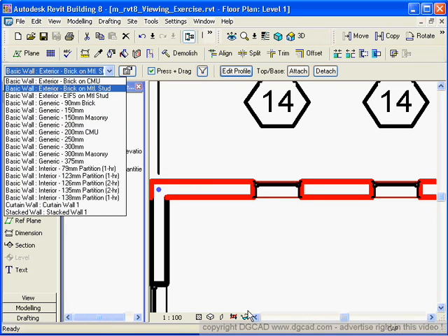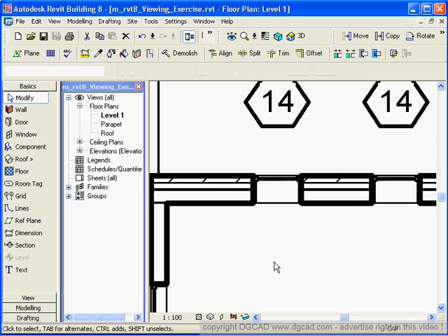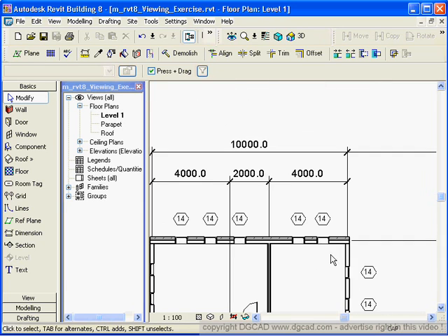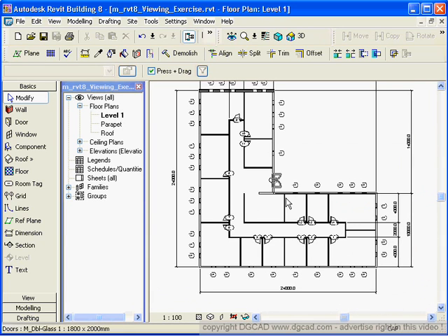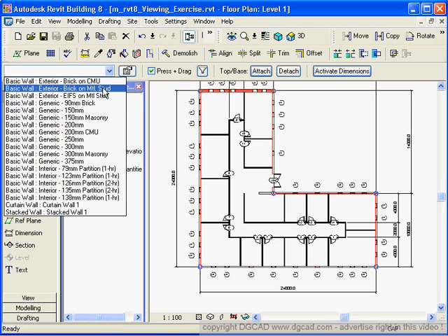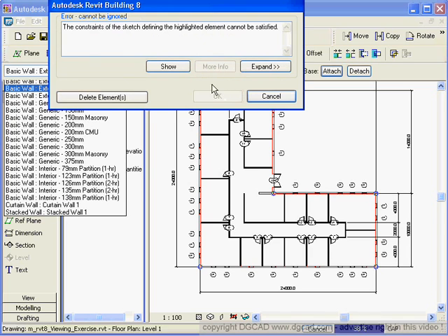But if I go in here and make this be a different wall style, of course, you're going to see, and I click out, and there's going to be an update in there. So that wall has changed. Now if I want to grab multiple walls, I can go in here, and if I hover over this wall and I hit my tab key, the tab key will chain all the way around the whole building, and then I can click on that, and then I can go back in here and say, okay, all of the exterior walls are of this type.